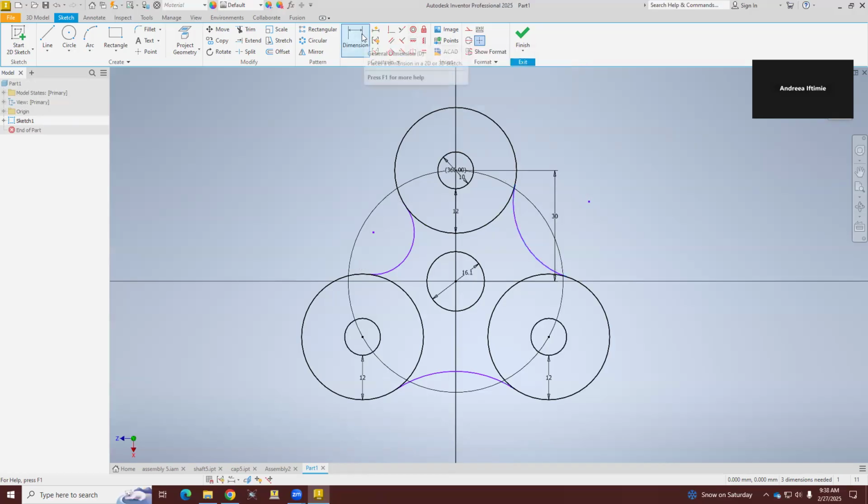with the dimension. And here was a little bit funny because depending on where you pick on it, it will constrain on different things. So I really wanted to constrain on the radius. So I had to click here, right? If you click in the center, you're constraining on the angle. So you really want to constrain on the radius. And when I tried it at home, it was 18, but I didn't have 12 for the circle. So let's try it, 18. Click on it, 18. That looks nice. So I'm going to constrain this one.